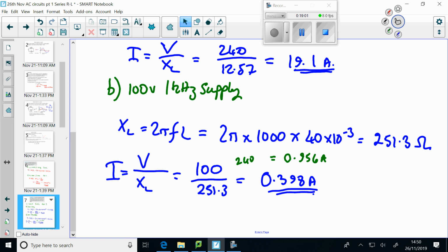All right. If you replace the AC coil relay mistakenly with a DC one, the circuit won't work. It won't energise because the impedance is too high. However, if you go the other way round, you put the AC one in the DC circuit, that relay will work for a long time. Depending on how often and how long it's energized for, it will work. But eventually the coil will burn out.